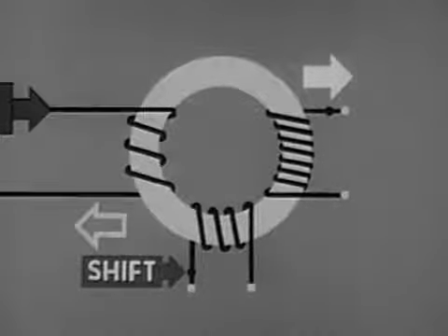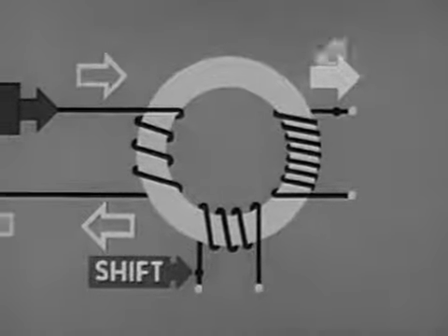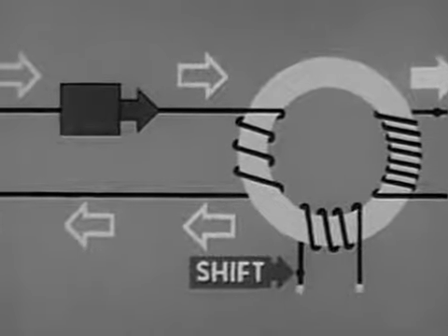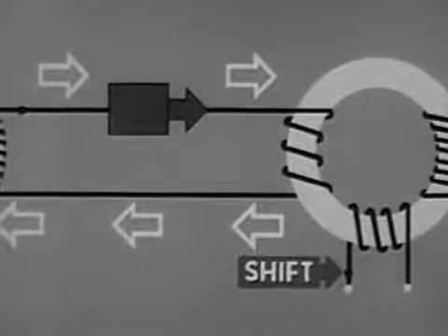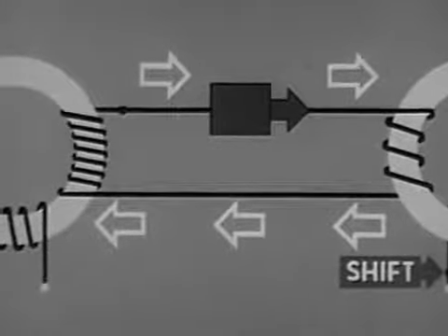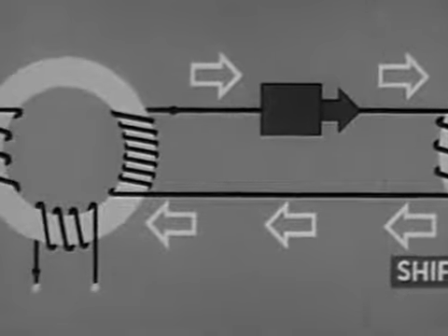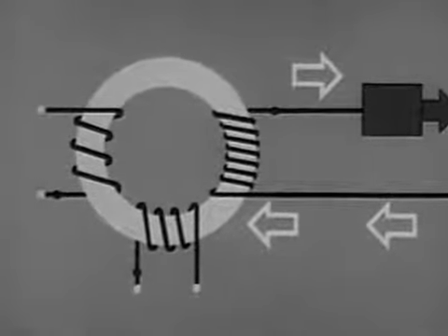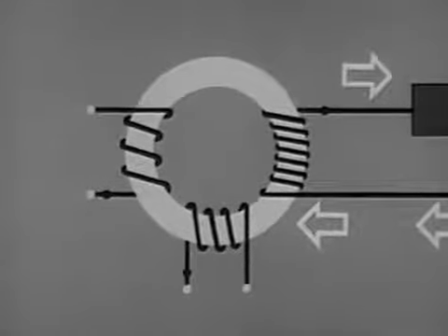Current will flow out of the dot side of the input back toward the first core. The one-way device won't stop it, because it's going around the circuit in the direction it allows. This backward flow of information would, if unchecked, switch the first core, interfering with its operation.